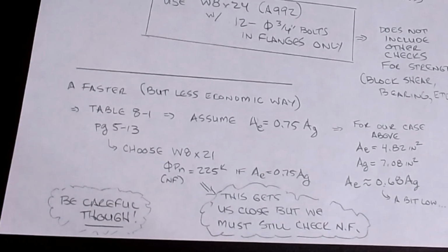So like I say, it's a long problem, and this video is a little bit longer than normal, but I hope it's made sense to you. It's a very important concept. We get to a point now where we can start setting up spreadsheets to automate this procedure, because you are in a mode of guessing and checking. Okay, but you can generate spreadsheets that will tally up these values for you, input, and then you can quickly verify what works and what doesn't. But those are a couple of methods that we can use in design to get first guesses on members, which now let us refine our model and thus refine our loads. And we're now into that iterative process, but at least we have a size to play with.